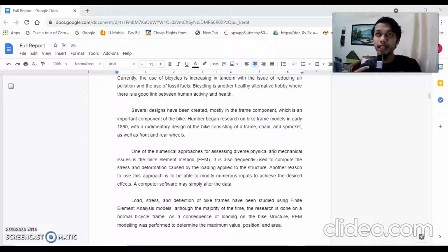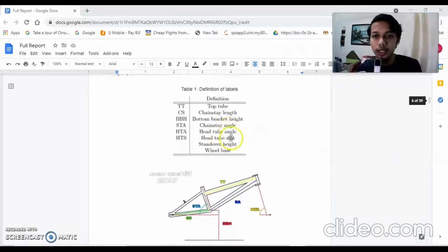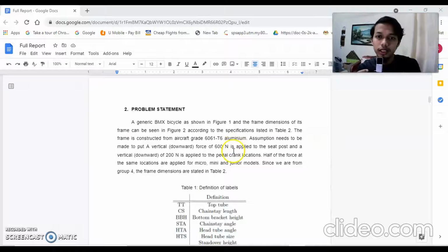To be clear, for case 1 and case 2 we have the same force but different diameter. For case 3, different force and different diameter, so that we can analyze what result the ANSYS analysis can give. For your information, our material is T6061 T6 aluminium. So let's go for the first analysis, which is direct stress.